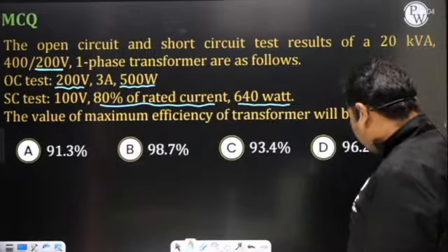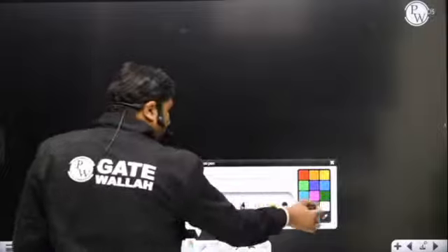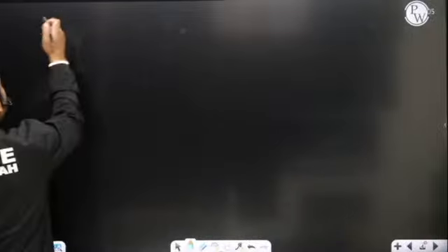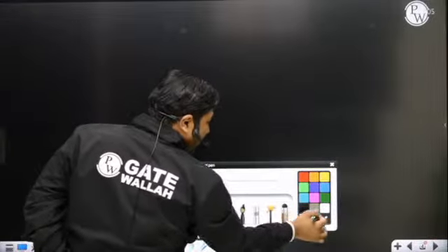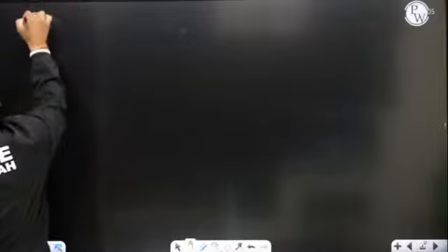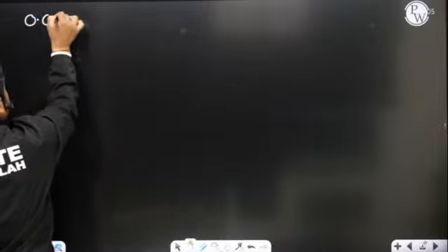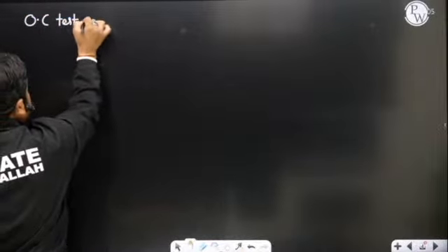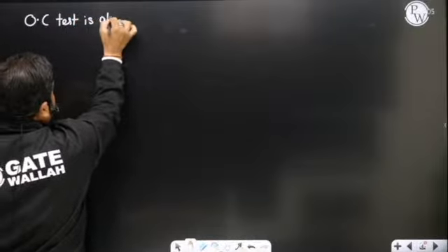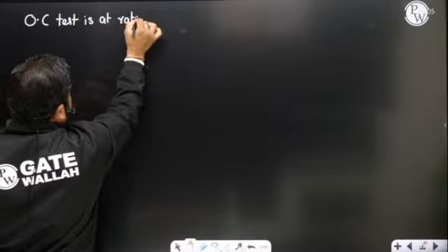Let me help you out. The open circuit test is conducted at rated voltage and rated frequency.